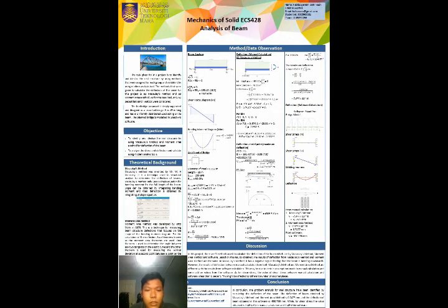However, the results of deflection from manual calculation, from both Macaulay's method and moment area method, are different from the result from software calculation. This may be due to certain assumptions made in manual calculation and some add-on values from the software. As for the shear stress, the difference between manual calculation and software is less than 1%, so this might be affected by different number of decimal places.